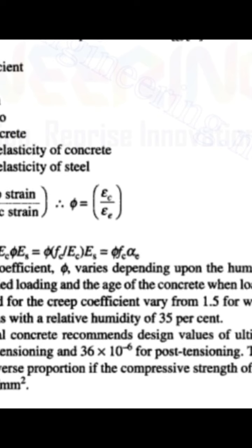Generally, the recommended value for the creep coefficient varies from 1.5 for wet conditions to 4 for dry conditions, with a relative humidity of 35%.